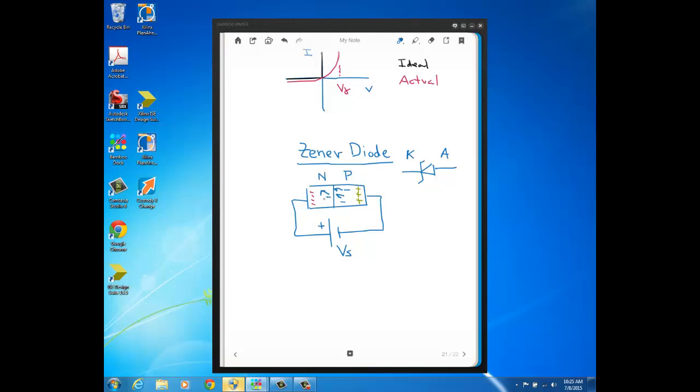And now you have electrons flowing through this junction, and if there's electrons flowing, there's also positive charges flowing. So as electrons flow one direction, as we've talked about and as you learned about in your circuit theory classes, the positive charges are going the other direction. And we've defined in this class, just like in your 201 class, that current is positive charge flow. So you see, once this ripping of electrons occurs, and when this occurs, it tends to happen all at once.